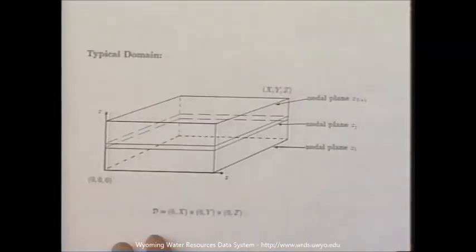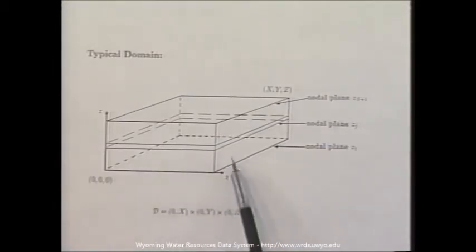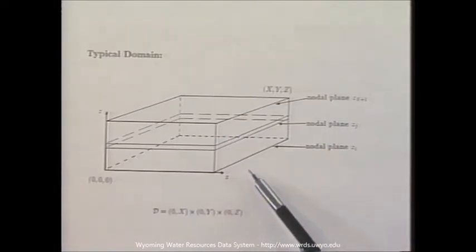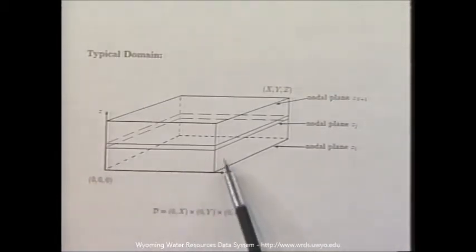Now, what Myron suggested is that one could do a 3-dimensional Fourier series. These are your fast Poisson solvers, for instance. However, you don't have that orthogonality, because if you change your hydraulic conductivity with respect to elevation, you start losing that. You also could have just a line representing the Fourier series on a particular line, and then do a 2-dimensional finite element technique on the rest of the domain.